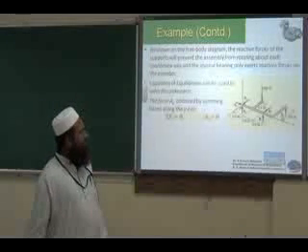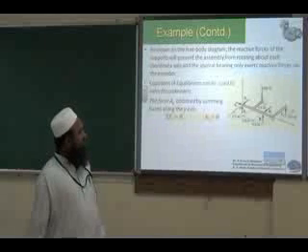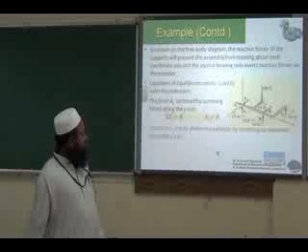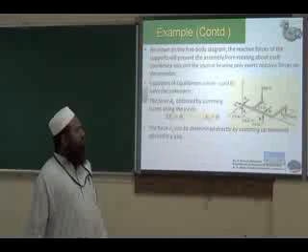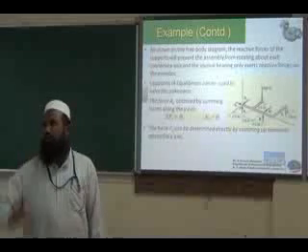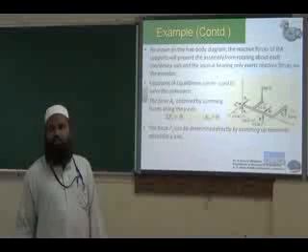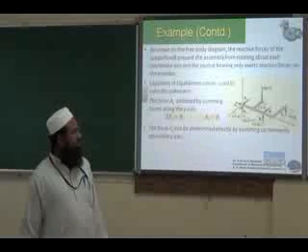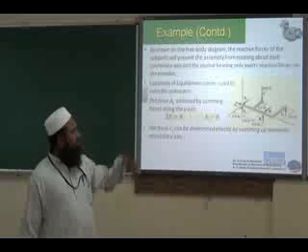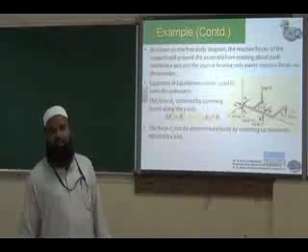Now we want to find Fc, Tz, Bx, etc. So Fc can be determined by summing up the moments about the y-axis. Now we take moment of all the forces about the y-axis. So Fc's moment is force times its perpendicular distance. Fc times its perpendicular distance is 0.6 meters. And this 900 force also has a moment about the y-axis, 900 times 0.4.